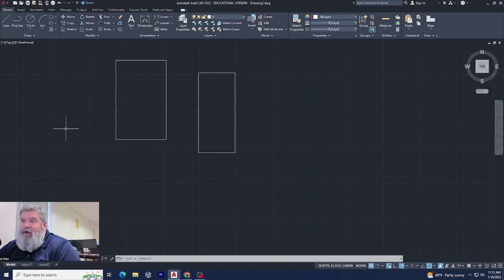Object snaps do not force objects to align with the grid and the snap. So AutoCAD provides a capability called Object Snap, which enables you to snap to existing objects, endpoints, midpoints, centers, intersections, etc. So, for example, these are your object snaps down here, okay?